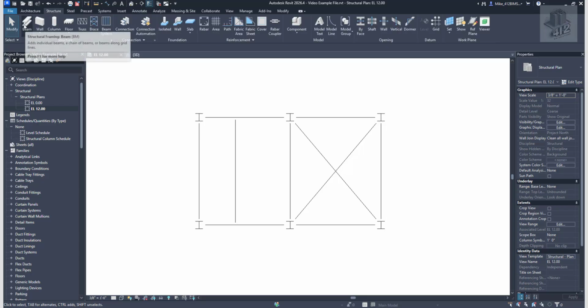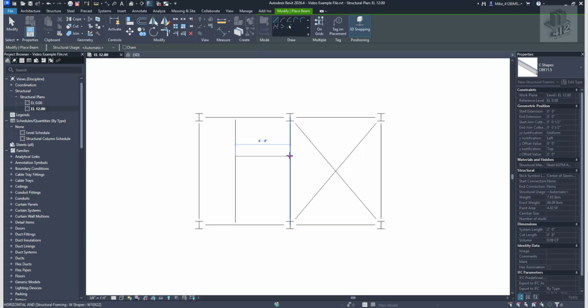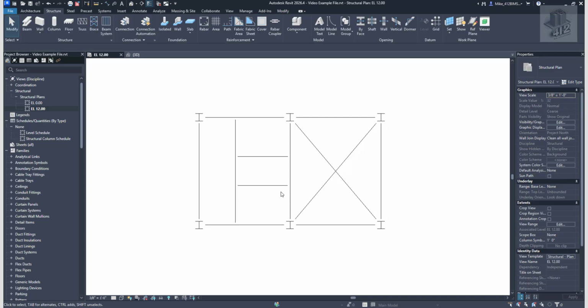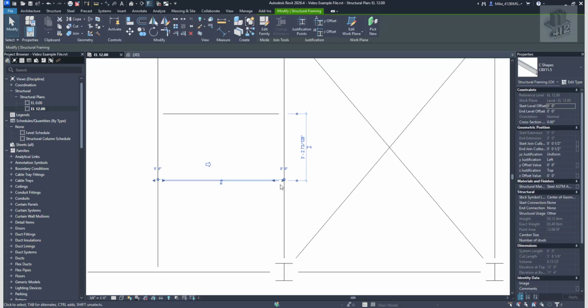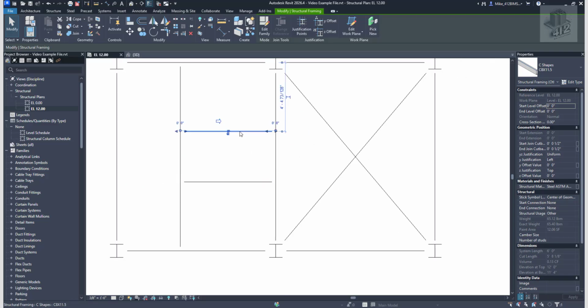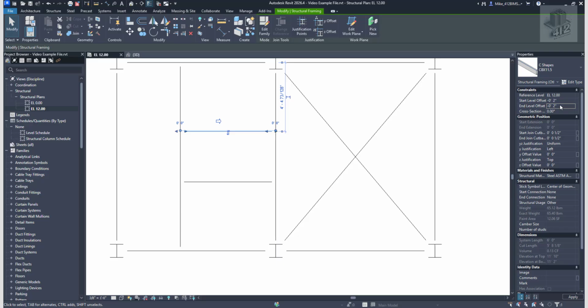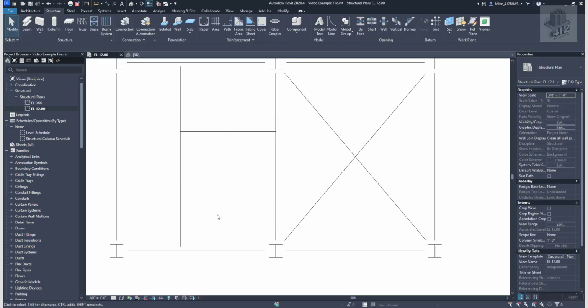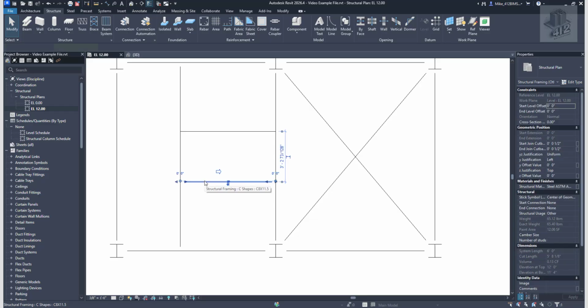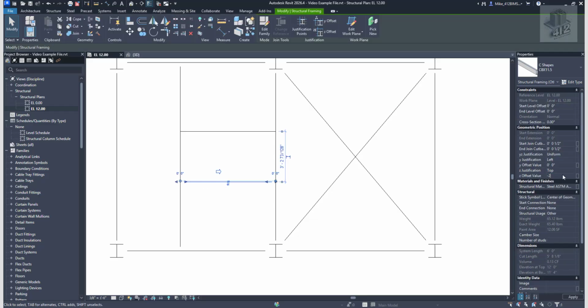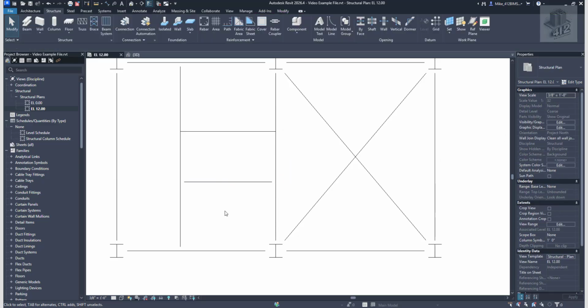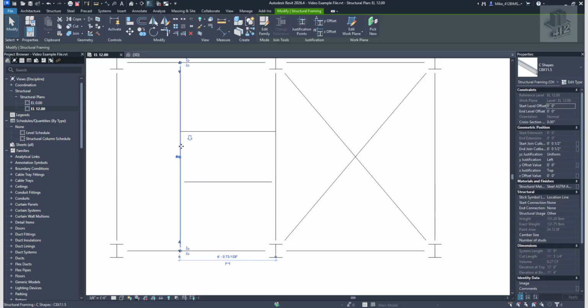So I'm going to add 2 new channels. I'm going to put one here that connects to this, and I want to put one that connects to this. And because they're actually connected, you can see the little cutback on it. If you were to change this to say -2 inches and change this to -2 inches, they're no longer connected. Now if you grab this one here and you give this a -2 inches, they are still connected. If this beam moves, the one that's connected will stretch.